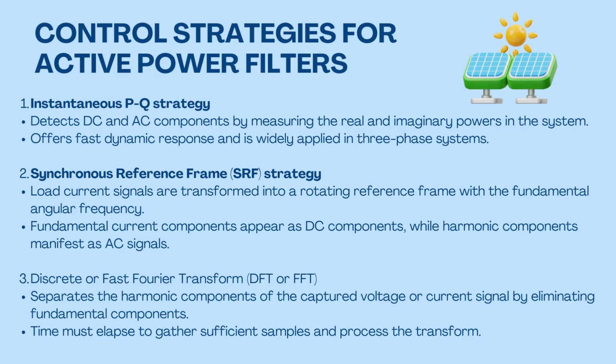Next, I would like to present the control strategies for active power filters. The first one is the instantaneous PQ strategy, which detects DC and AC components by measuring the real and imaginary powers in the system. This strategy offers fast dynamic response and is widely applied in three-phase systems.